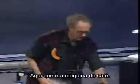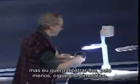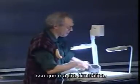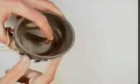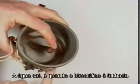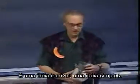Here is that coffee machine. It's not working anymore. It's a very old one. But I want to show you at least that bimetal. This is that bimetal strip. Water goes in here, you heat it, and when it's hot enough, the bimetal lifts up, and you can see there is a hole there. This is the hole. And the water comes out, and when the bimetal is closed, then it closes off that hole. So it's an amazing, simple idea.